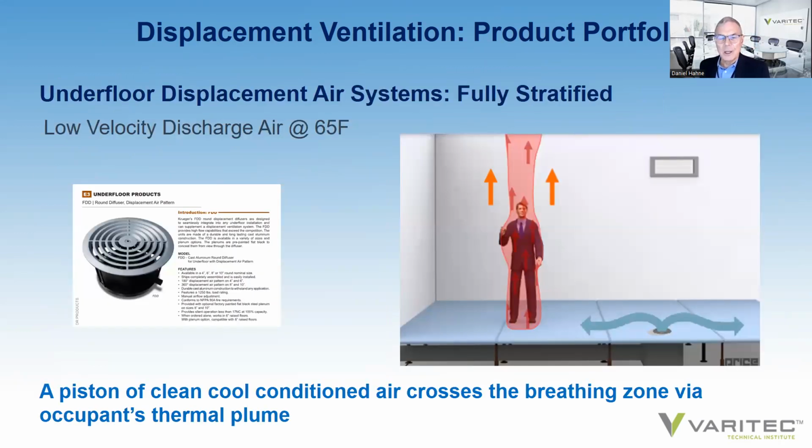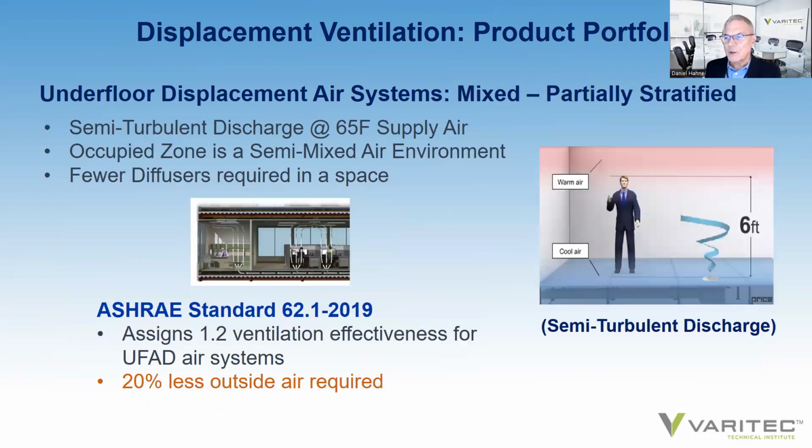Another excellent solution, and a solution that I think really hasn't gotten its due recognition, and I sort of understand why, and there's a good reason why I won't go into right now because we'll cover it in the underfloor presentation in December. And those are underfloor air systems. Underfloor air systems do create thermally stratified environments. There is a proper, fully thermally stratified environment offered when an underfloor system uses a displacement style floor diffuser. These diffusers will probably inject roughly about 50 CFM per diffuser, maybe 45. So you need a number of diffusers to provide the amount of air necessary to condition the space.